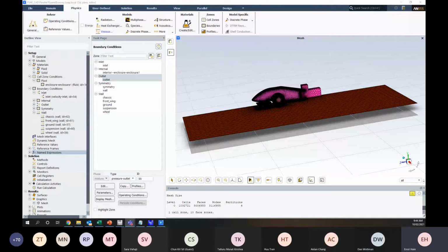Complex expressions such as exponential powers we just went through. What about avoiding reverse flow in internal pipe flow? Sometimes, like I say, it's not able to be done, and sometimes it's not such a big deal. It depends on the size of the domain. Obviously, you're solving for the physics of the problem, so if the flow characteristics are a function of the physics, you can't necessarily do anything about it if you can't make the domain big enough that you're not getting reverse flow, or the setup of the situation is such that there's always going to be reverse flow.